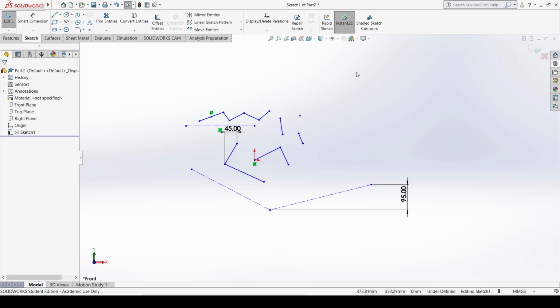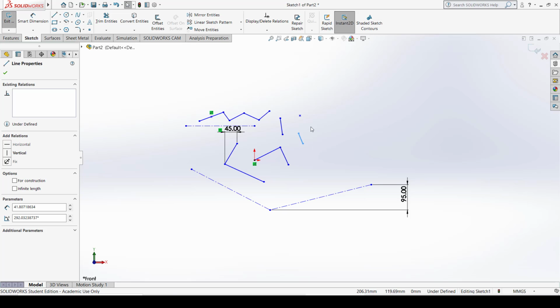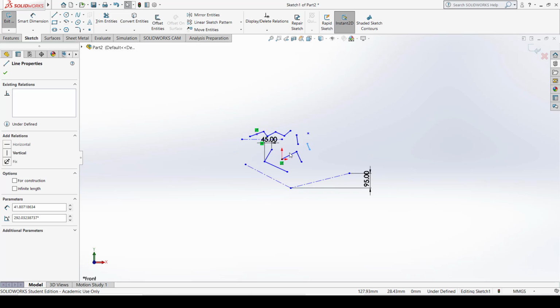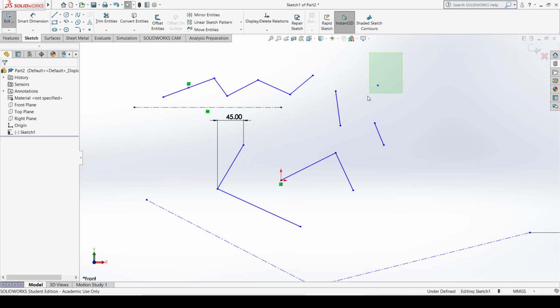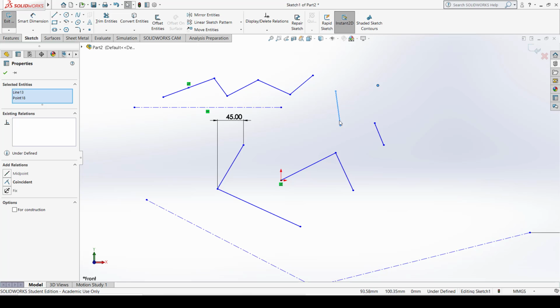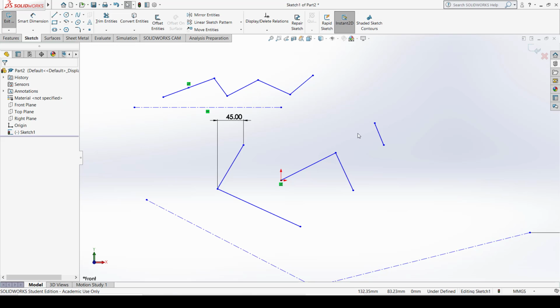Now what you do is drag this window so that it touches the element. Any element touched by this window is completely selected. See, I can show you. This is the window. When I touch this line anywhere, on any point, on the side of the line, or whether it's half the line or any portion of the line that is covered by this window, the element is fully selected, and you can delete the element by pressing the delete button. Okay, now